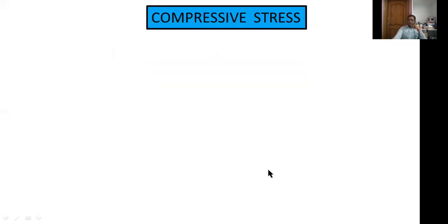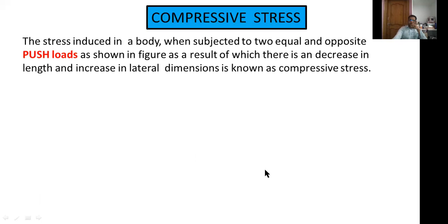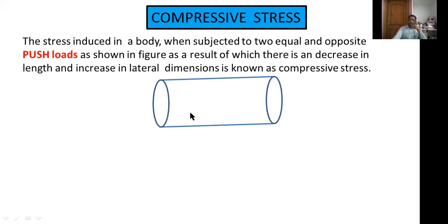Now coming to compressive stress. The stress induced in a body when subjected to two equal and opposite push loads. These two are push loads, equal and opposite in direction and acting along the axis of the component, as a result of which there is a decrease in length and increase in lateral dimensions. This is known as compressive stress.